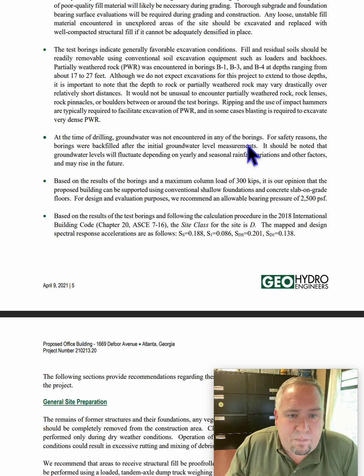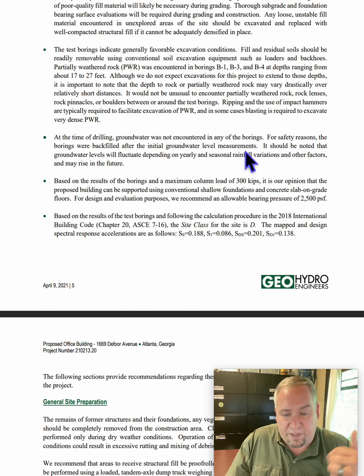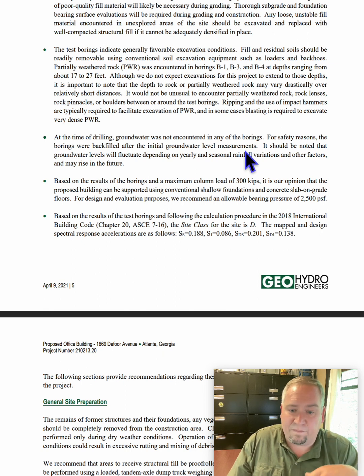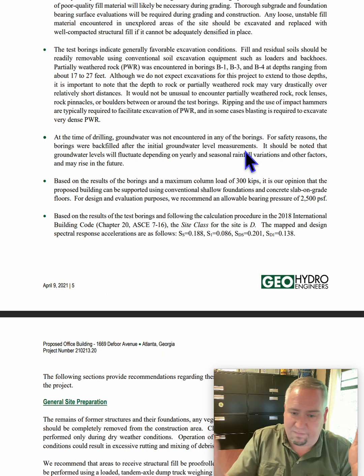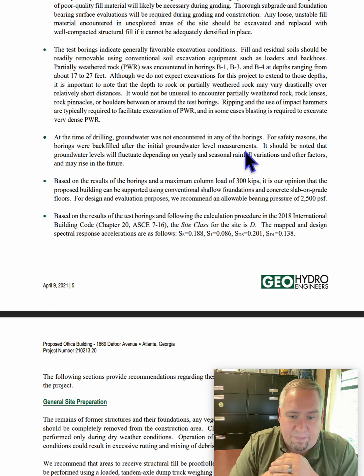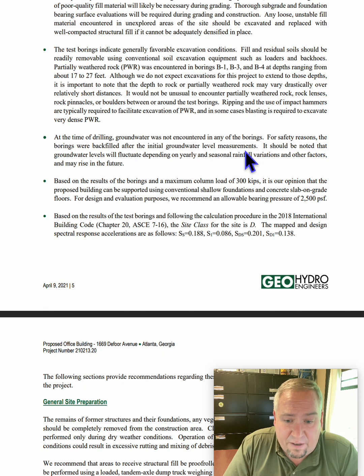For safety reasons, the borings were backfilled after initial groundwater level measurements. Now remember what I said earlier. Sometimes you get there and find them. Well, they went so deep, they didn't want kids or animals falling down in there. I've saved two animals out of a ditch one time. I actually saved a baby deer. So squirrels, chipmunks, you don't want anything falling down in there. So sometimes these guys will backfill them, sometimes they won't. You can still look at some of the residual soils because it doesn't fill it all the way back up. But when you're walking out there trying to find them, if it's filled in, you won't be able to see too much.